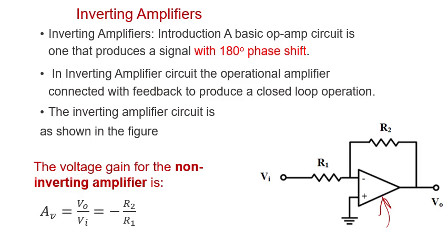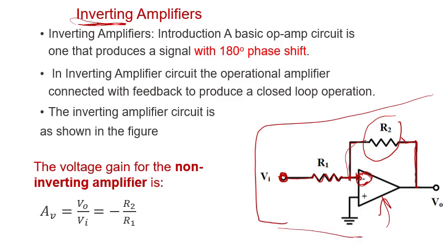the circuit of R2 and R1. So R1, or the input signal, is sent to the input, which is the negative terminal. That's why we call it inverting amplifier, because we are connecting it to the negative input. We will see what the result is. Beside that, there is another resistance connecting the output to the input, through resistor R2. We call it R2 or sometimes RF. So whenever I have this arrangement, this is called inverting amplifier. Keep in your mind the positive is to be grounded.